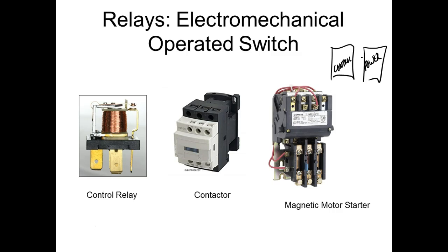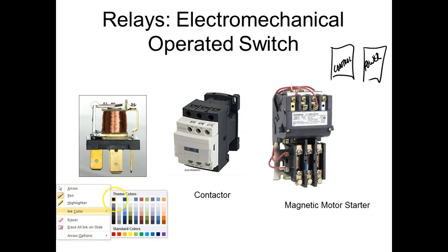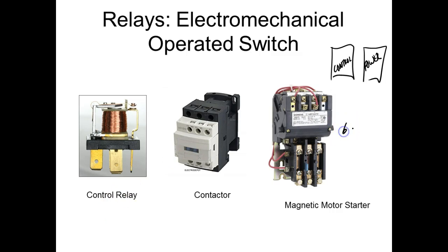So if you don't know the start current of a motor, when a motor's sitting still and you start it, it pulls an inrush. It pulls a lot of current. The rule of thumb is 6 to 8 times. That's why they said stop flipping the light on and off. Good. 6 to 8 times. So if it took 5 amps to run it at its rated horsepower, then it could take 30 to 40 amps just to get that sucker started.